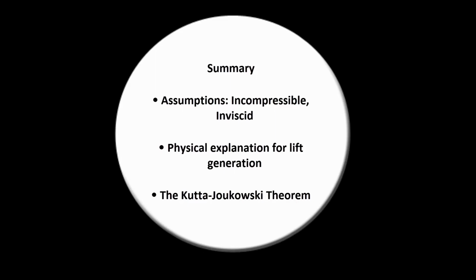And through Bernoulli's equation, this gave a net imbalance in pressure, which resulted in a non-zero lift force. This mechanism was the same way that airfoils obtain lift. We then learned that the Kutta-Joukowski theorem allowed us to calculate lift from any flow with a known vortex strength. And this makes it a useful tool for designing high lift airfoils.